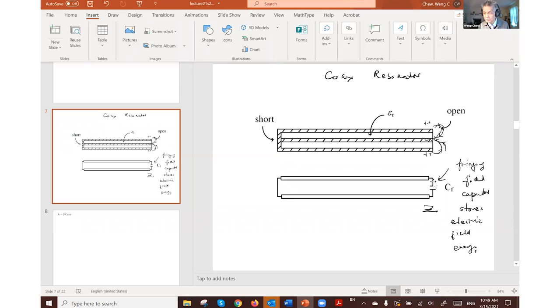Well, if you were to put in a capacitor here, you will have some transcendental equations to solve. Okay, so one way to solve transcendental equations is to use graphical methods, but I'll leave it for you to play around with if you're interested in finding the resonant frequency of this transmission line. But when this is an open circuit, finding the solution is trivial.